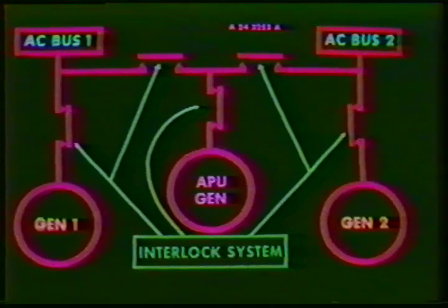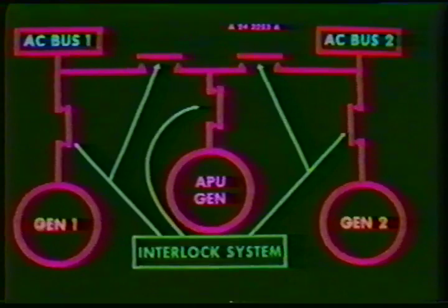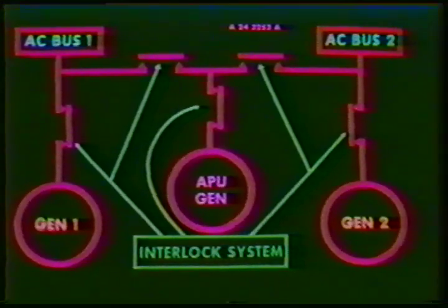The interlock system ensures the transfer. In normal operating conditions, the AC load buses will be supplied by their own generators with the transfer relays open. Transfer logic ensures AC load bus operation without paralleling generators.